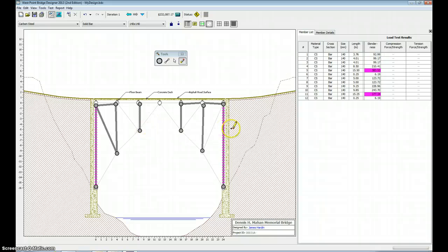But once you've designed your bridge, there's several things that I want you to look at. Over here on the right, you're going to have a list of all the different materials that you're using in your bridge design, and it's going to provide for you load test results. You notice I have two errors here. These are on the vertical lines that I have on the ends of the bridge, so you would need to analyze what's going on there. You also have all the different construction materials here that you can select from that you want to use. You're going to have a calculator that's going to tell you the approximate cost of construction for this particular bridge design. And there are a lot of other features here that you can work with.